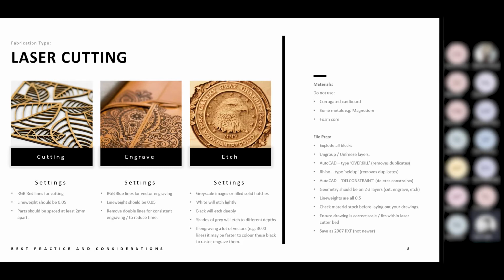But again, in terms of file prep, if you're exporting this from AutoCAD or Rhino, which are the two software packages I would use for fabrication, you should always explode your blocks, because otherwise they'll come into the laser cutter software all black. You won't be able to read the color of the vectors or the line weights. So explode all of your blocks.